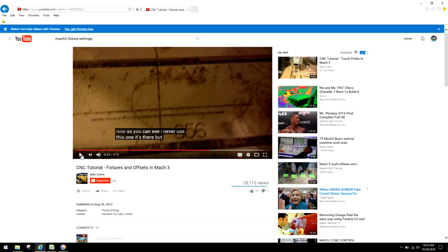It's there. Now, guys, actually what he did on this table, and this is the only reason I'm stopping this, is very interesting. He actually engraved in the spoil board where his fixtures are. That's actually a very good idea. The only thing I kind of would disagree with, or would be looking for more precision, because I am who I am and I'm trying to make parts as precise as I require them, and again, this is totally up to the end user, I would not just engrave a line in the table. I would facilitate a jig that I could actually place in those engraved areas, and make a jig so I can actually put the raw material in the exact same location.